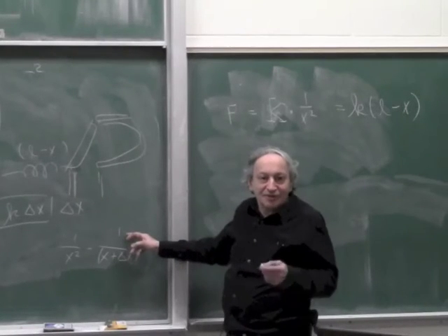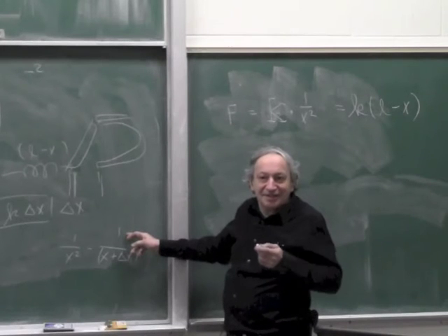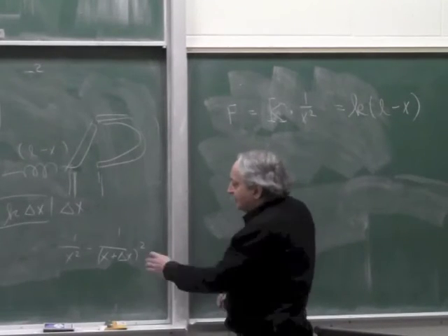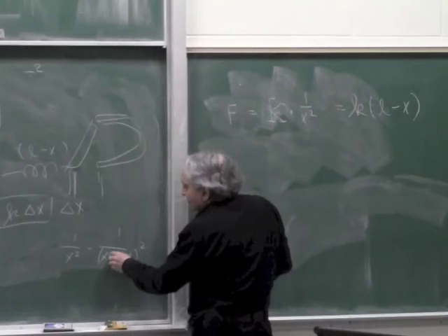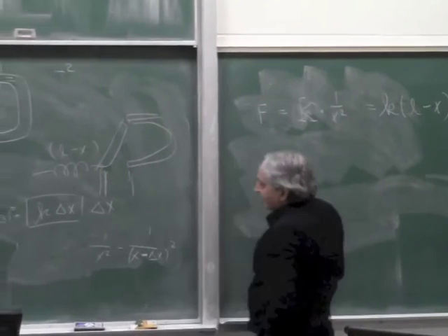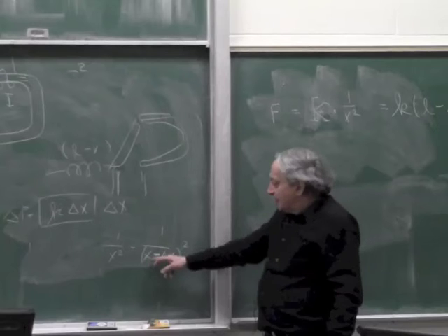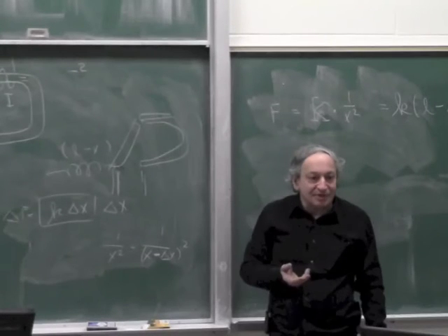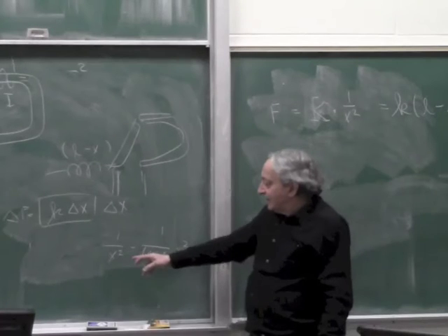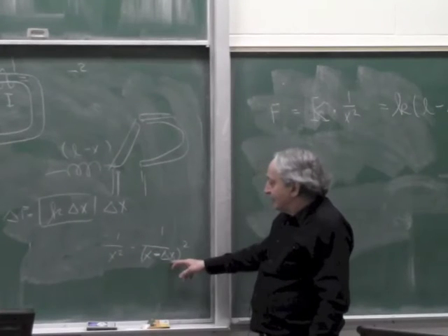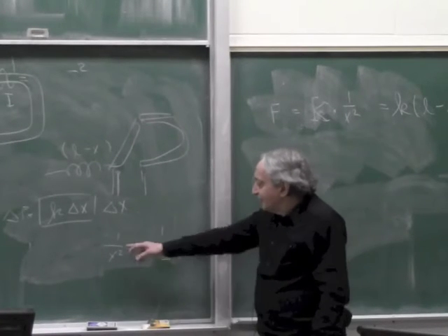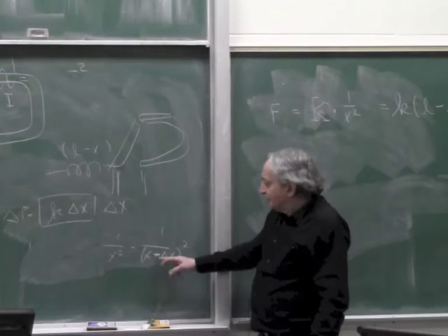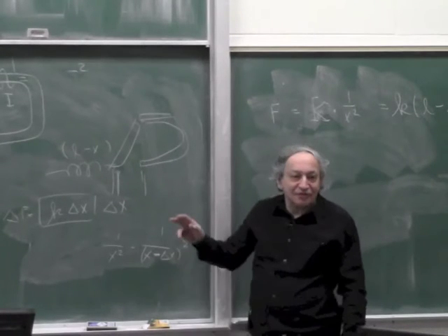So not only is the force nonlinear, but the increase in force when you add delta x or remove delta x, actually here x minus delta x, I should draw it with a minus because the x goes down. So if x is much larger than delta x, this number can be as small as possible. Imagine if this is like a centimeter and delta x would be a micron, this increase in force will be tiny. But when x approaches 0, this increase in force will approach infinity.